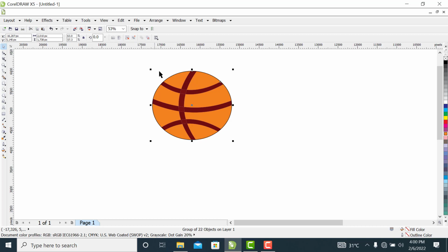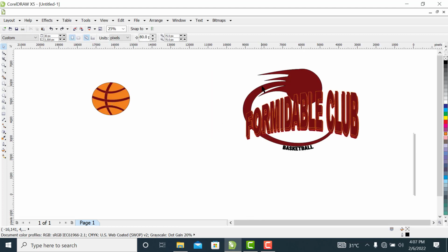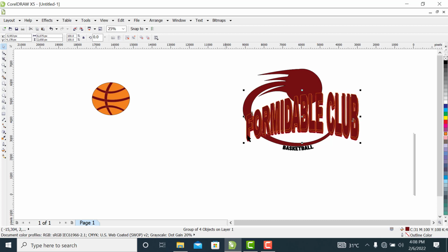All right. So now I can go back to our logo. Then I will insert this into it. So before I insert this ball in here, I will need to group the two texts together, the duplicate and the original text, right? So I'll click on the duplicate, go to the tip, click on it, hold down my shift key and click on the original, then Control G. It has been grouped together to become a single entity. So that is that about that. Then I can adjust it a bit, or better say, I make it smaller.